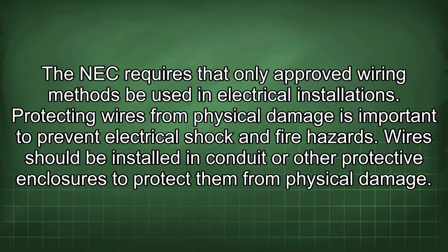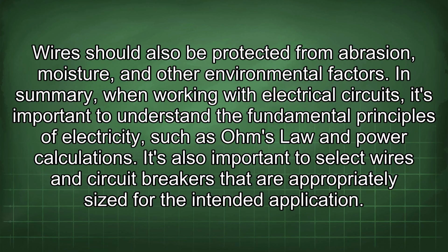Protecting wires from physical damage is important to prevent electrical shock and fire hazards. Wires should be installed in conduit or other protective enclosures to protect them from physical damage. Wires should also be protected from abrasion, moisture, and other environmental factors.